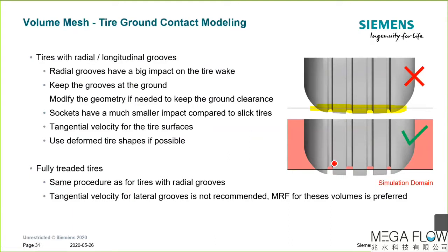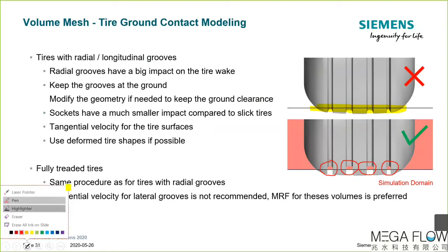What you should do is make sure that you're keeping the longitudinal grooves at the ground. They are extremely important because they enable a pressure decrease between the front and the back of the contact patch. And that's extremely important for the aerodynamics, for the wake structures of the tire. As you can see here, it's the same geometry, but I just created a subtract in Star-CCM+ to make that happen. You can also do that. It's really important that you respect these rules.